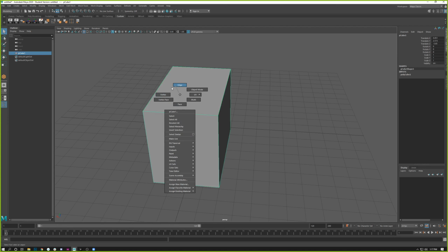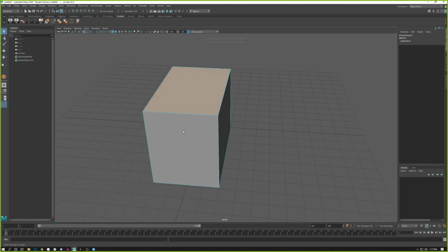So you can use the marking menu, and again, I'm a fan of quick keys, so here are some quick keys also. The F8 key will allow you to toggle between object mode and whatever subcomponent mode you were in last. In my case, I think it was face. Alternatively, you can hit the F9 key to go straight to Vertex mode.